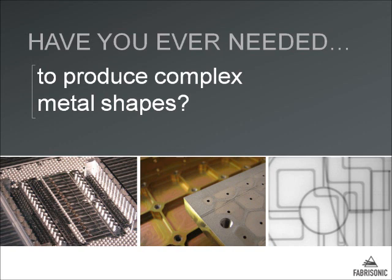So in the aerospace industry, you often have the problem of buy to fly. That means you take a large, thick section of material and machine away 90% of it to make a component. Using additive manufacturing, you can take a thin plate and add material just where you need it so that there's not so much waste of billet material.